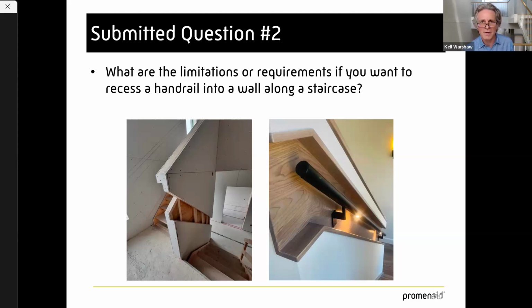So if, for example, you were to have an aluminum screw in a stainless steel handrail, it would corrode very quickly. If you have a stainless steel screw in an aluminum handrail, it will never corrode, because the small item, the screw, is going to be stainless steel. It's going to be higher up the electrolytic chain, and it's not going to be affected. So that was a very important, conscious design effort to make sure that the stainless steel is in the screws, and the aluminum is in the handrail.